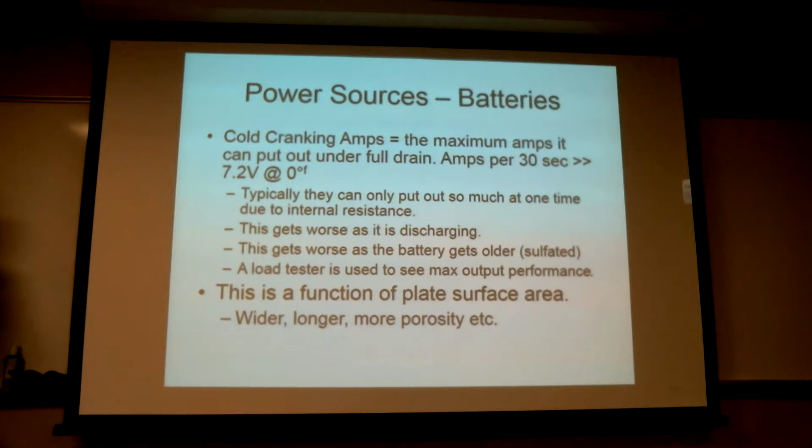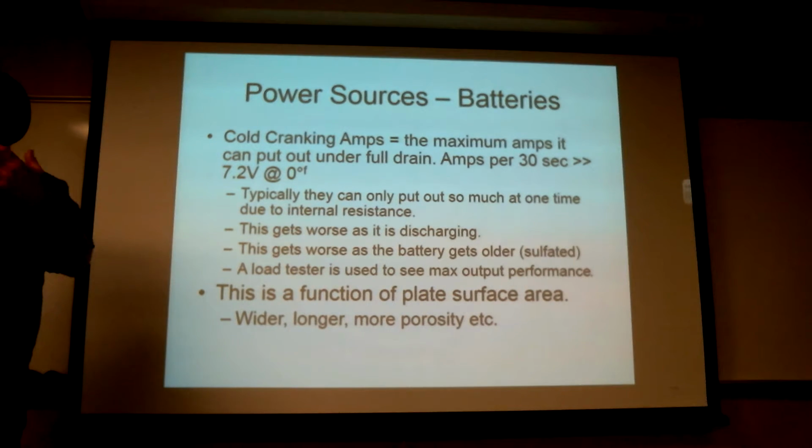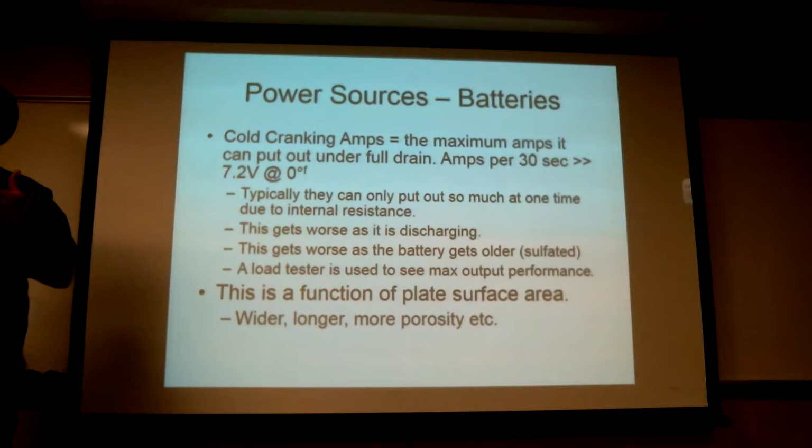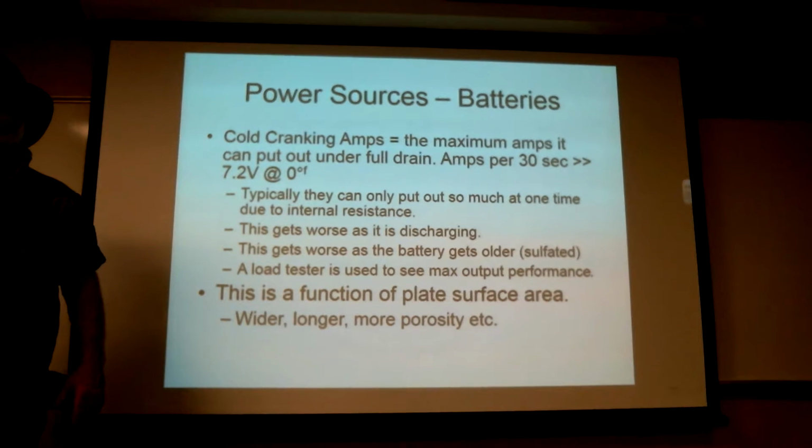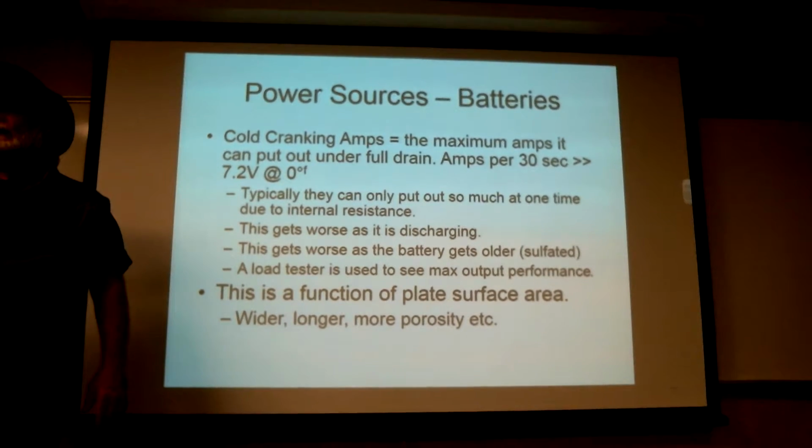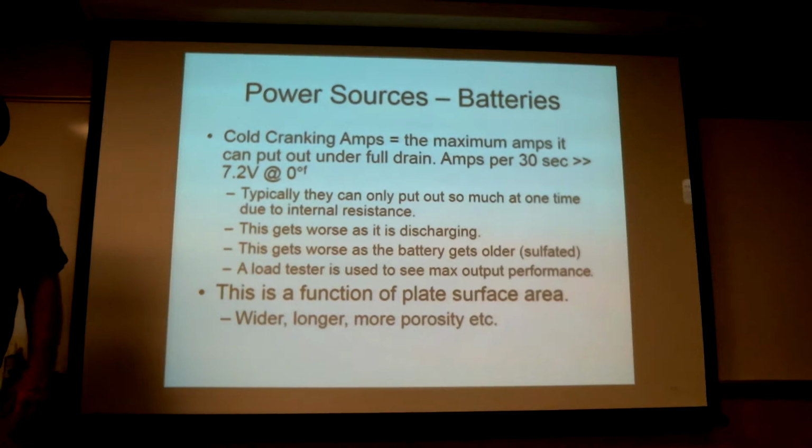If I want it to really deep cycle, I'm going to put a whole lot more plate area in there, but I'm going to make it structurally a lot more robust and sound so that it can deeply discharge without structurally falling apart on us, particularly on the recharge. This is changing the thickness of the sheets. The entire nature and structure of the sheets, yeah.